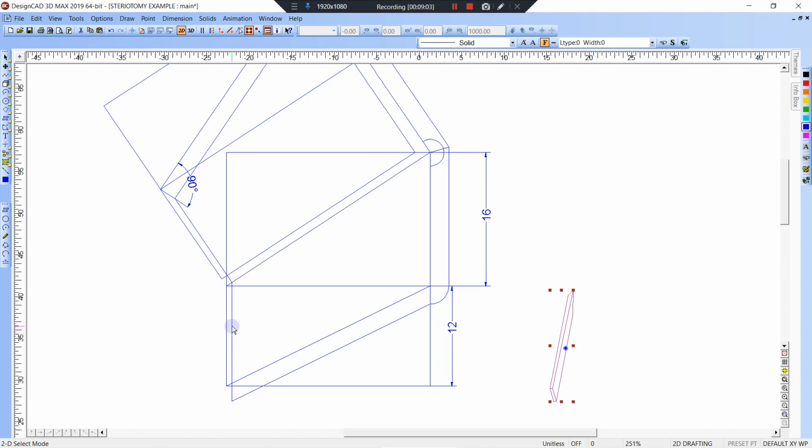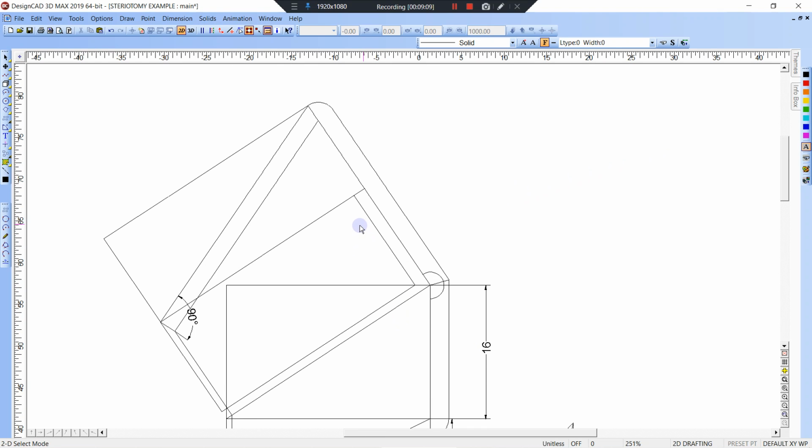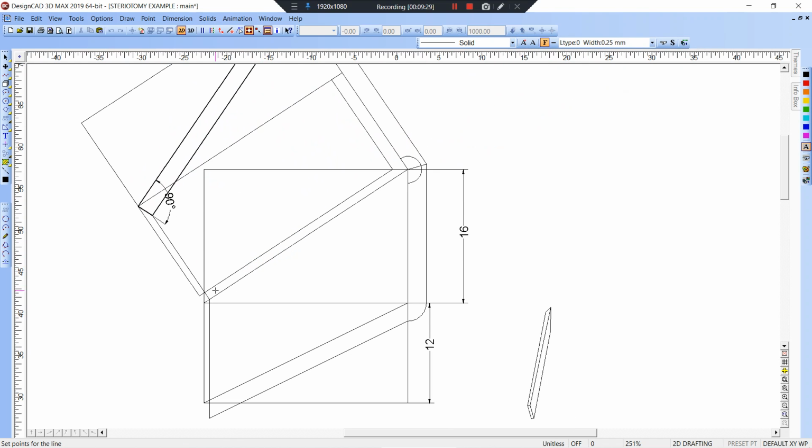And let's do this, Control A, turn it all black, hit apply, and let's start darkening in the true members. So V, all we're going to see of this one, since it's perpendicular, is that. Let's make it with width of 25, okay, apply, enter. This one here, let's see the same thing. This is the true plan view for, and this is actually, I messed that up, right? This should be up in here.